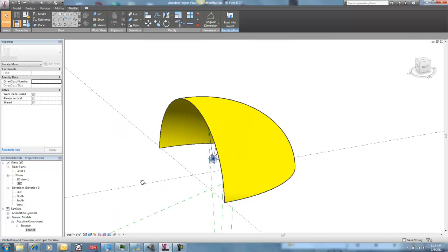Well, if I select those guys and I connect them with a spline by point right up here, now I've got a line that this line is always going to go straight off of whatever surface I load it onto. And I can actually even go like this, just to sort of give myself some more things to see. And I can test this out in the family that I was already playing around with. So I'm going to load this back into my band shell element here. So now I've got my 2-pick family, and I can just pick out in space somewhere here and pick on the surface.